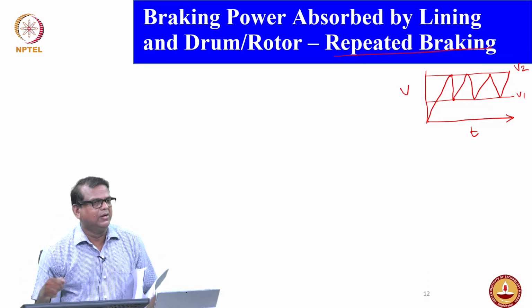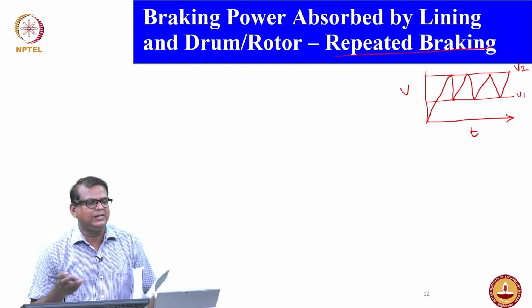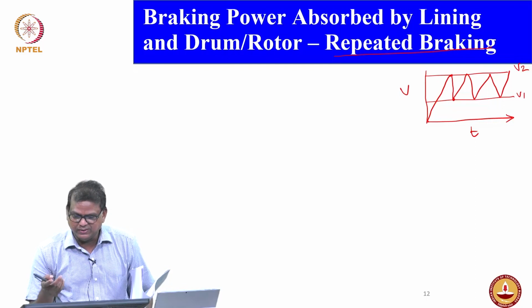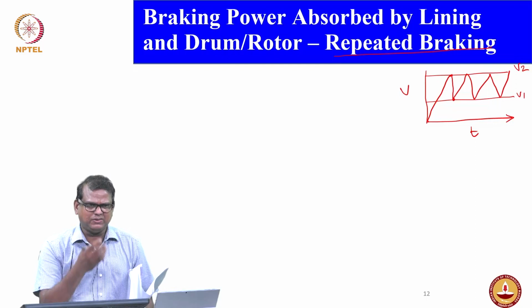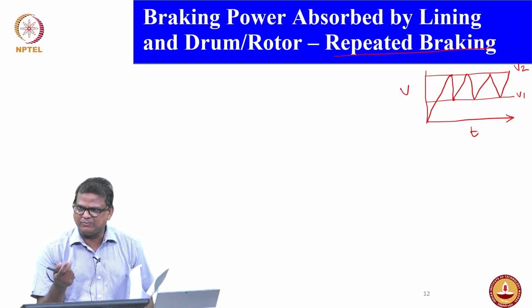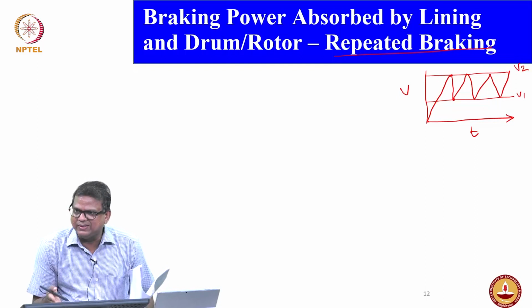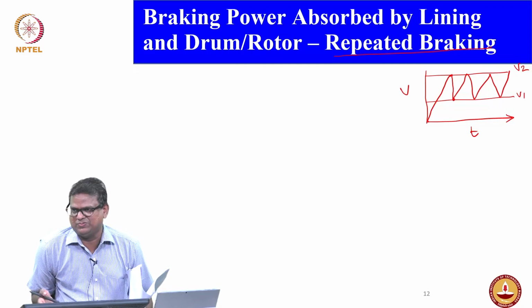So, in this phenomenon, would you expect any heat, any cooling aspect? Obviously, you expect the cooling. So, we have to consider the cooling. Earlier it was very easy: whatever heat was generated was absorbed by the brake lining as well as the drum. That is not the case now; you have to account for the cooling also.